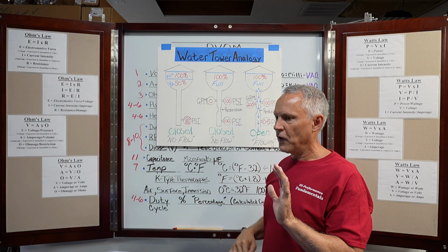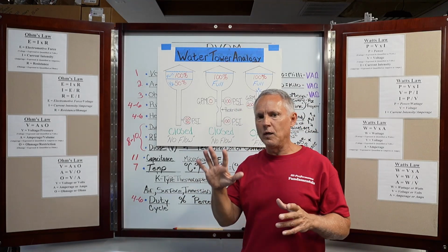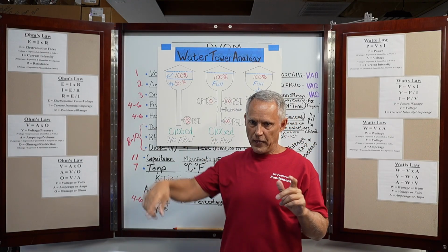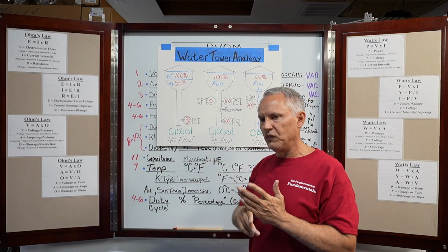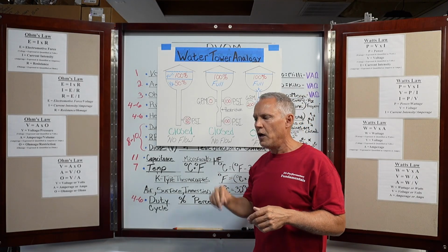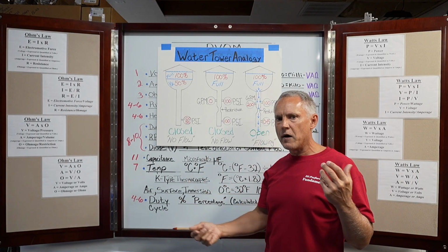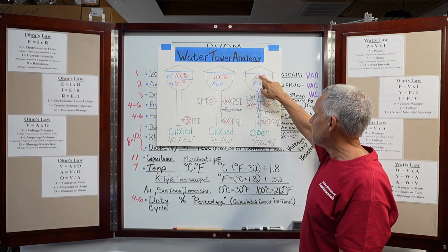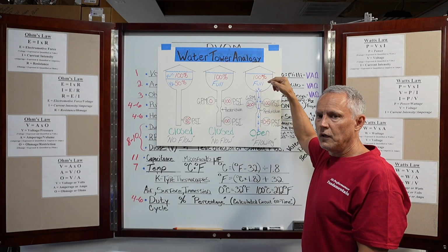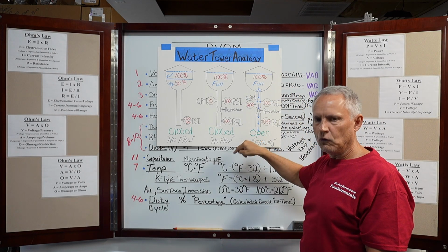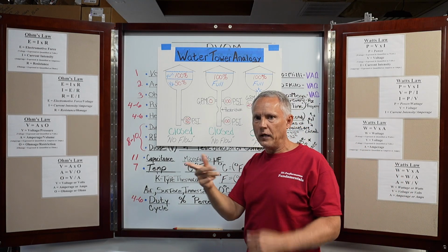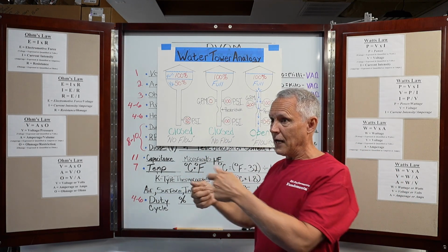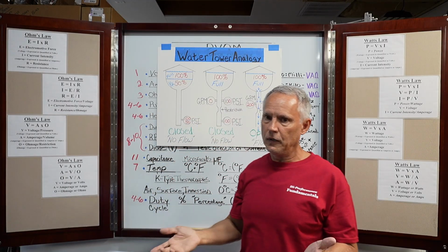Now, I'm not going to get very technical about that. I know we can get into polarity when you start talking electrical polarity. It's actually negative to positive. But in an automotive system, when you're placing fuses, you're putting in grounds, you're creating a circuit, you're going to be putting it in such an order that positive through the fuse, to the load, to the ground, or back to the battery. That's the way you're going to create the circuit, positive to negative. You don't create it the other way around. Let's create the negative side and eventually we'll create the positive side. That's not how you do it.